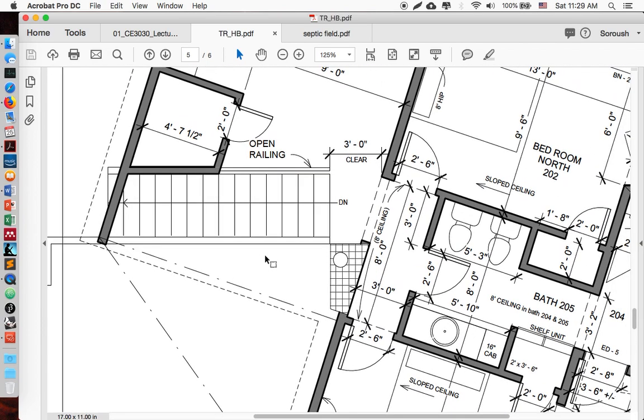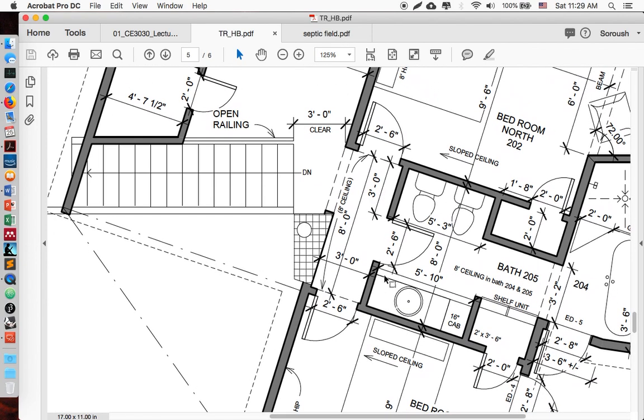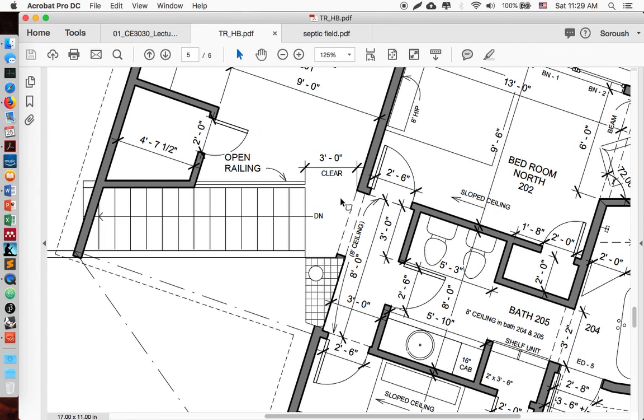As we move on and set different settings for line weight, you get used to that hierarchy of line weight, or line thickness, for different elements. If I want to categorize them, I start with the walls that cut through, then the lines that I'm seeing from the top.